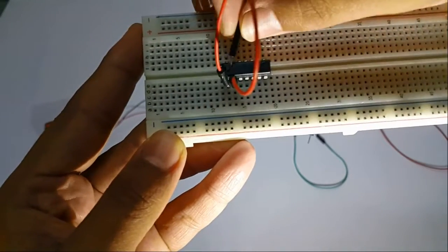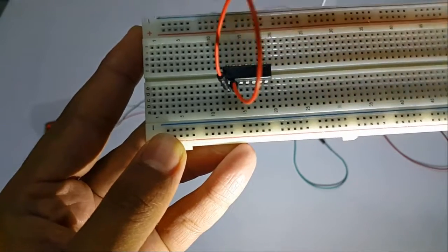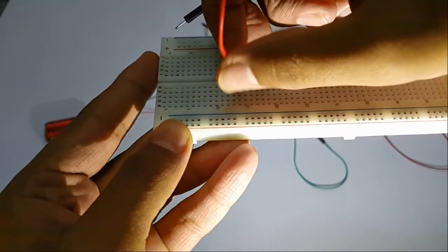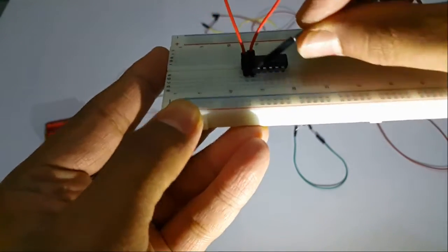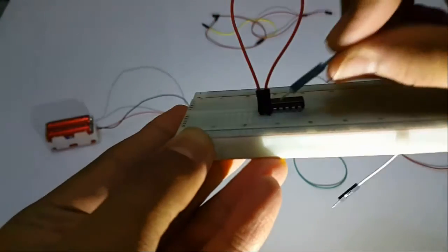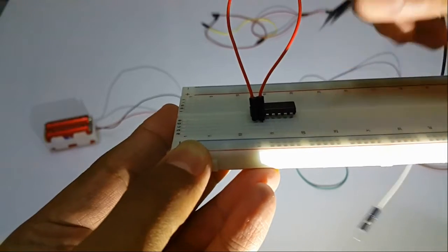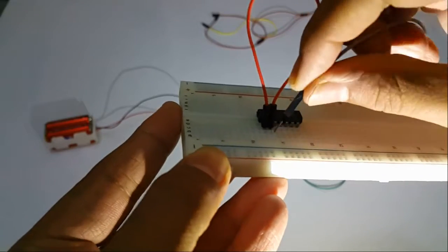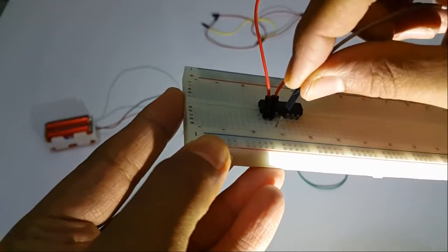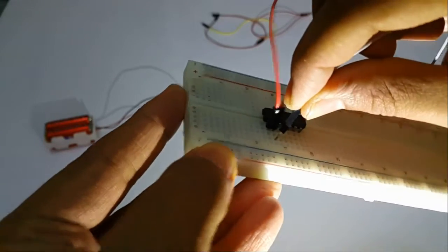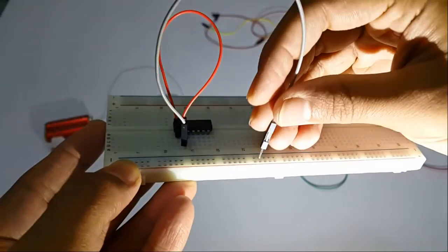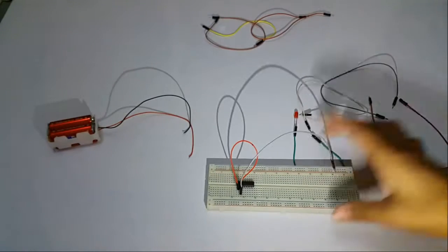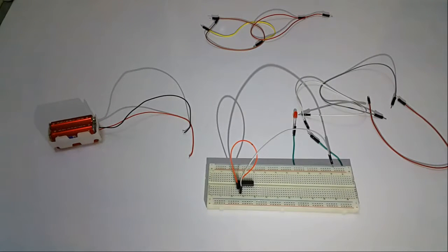You see this one and this one are the two inputs of the NAND gate, input A and input B. By connecting these inputs with each other, now this input becomes one. These two inputs became one input, either input A or input B. So just by connecting these inputs with each other, this becomes one input, and we will take either from here or here, in this row or in this row, and connect a wire and place it anywhere, by which we are going to verify whether it is a NOT gate or not. So this was all about making the NOT gate from the universal NAND gate.